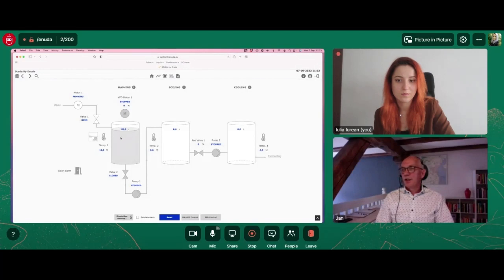We're using a very simple trick here, that all process values are highlighted a little bit, have a bigger font, and they are dark blue. We have another trick here where you see the motor started now, so it changed its state. So it changes color, and I can actually simulate an alarm on that motor. So that looks like this. So we have all the alarming logic behind all of this.